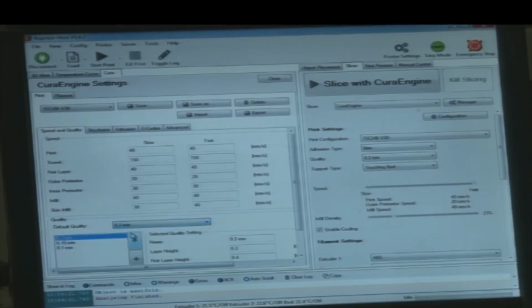0.2 mm means that it consumes less time, but the quality goes down. Sometimes our dimension or profile shape is what is important. If the quality factor is not very important and only the profile shape matters, then we can go for replica printing, that is, 0.2 mm can do. Sometimes we feel that the size and dimension as well as the quality that we need to keep has to be higher, so we can keep 0.1 mm layer thickness.